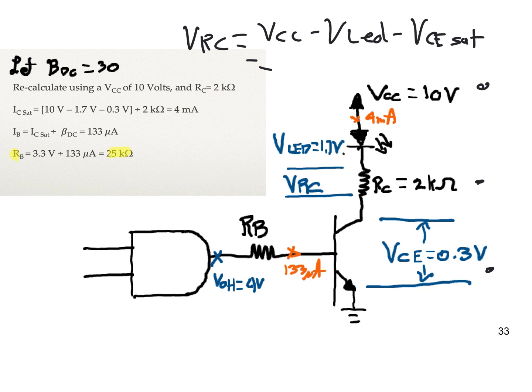So that equals 8 volts even. Okay, 2K ohm resistor, right? You get your 4 milliamps of current. If you wanted more current, just lower the value of RC.